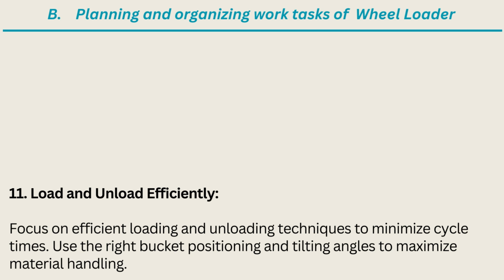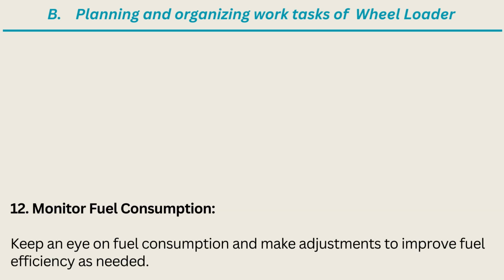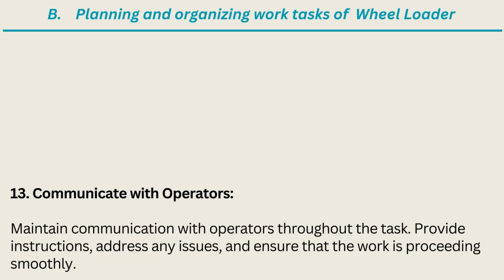Use the right bucket positioning and tilting angles to maximize material handling. 12. Monitor fuel consumption. Keep an eye on fuel consumption and make adjustments to improve fuel efficiency as needed. 13. Communicate with operators. Maintain communication with operators throughout the task. Provide instructions, address any issues, and ensure that the work is proceeding smoothly.